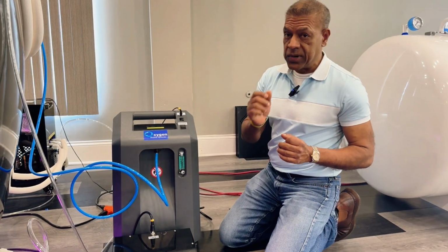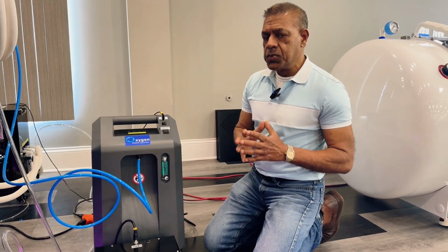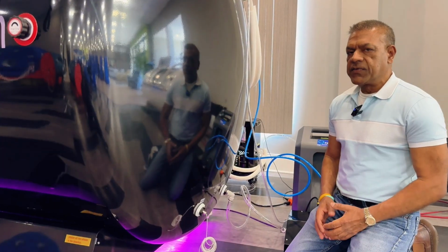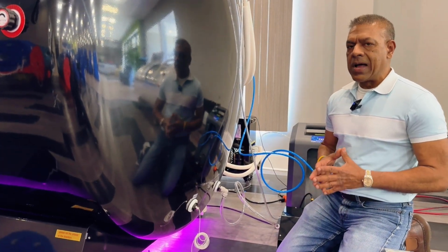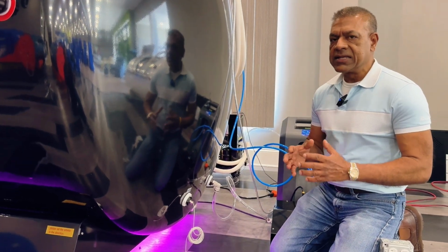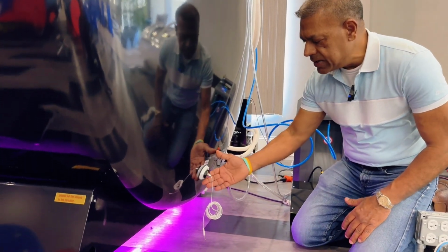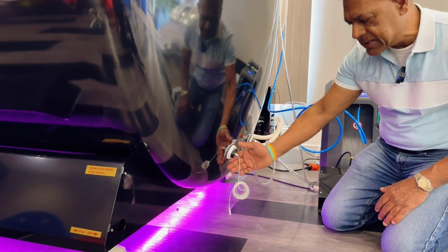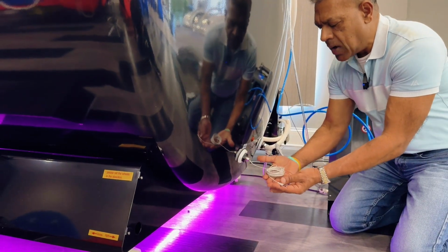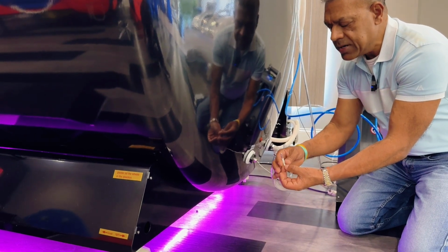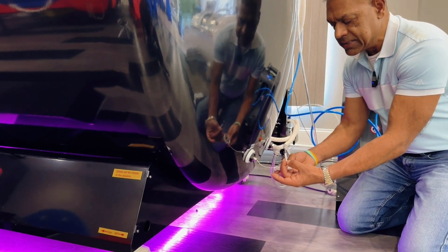Now, next we will talk about the grounding of the system. It is very important to keep your system grounded at all times when you operate the machine, and that is achieved by having this grounding wire, which is marked clearly, that says grounding mat. This wire should be plugged into the grounding port of your wall outlet.